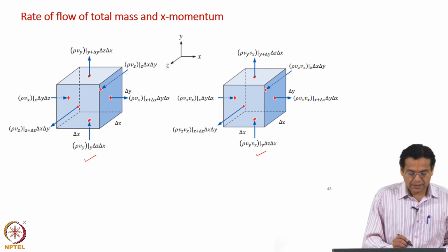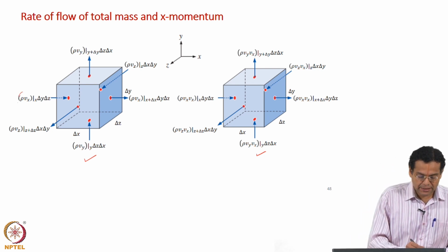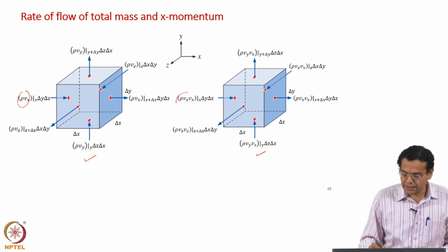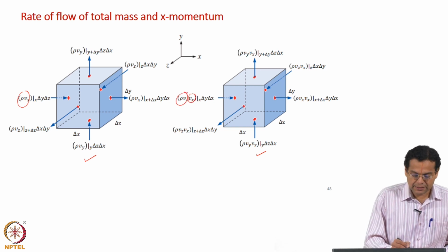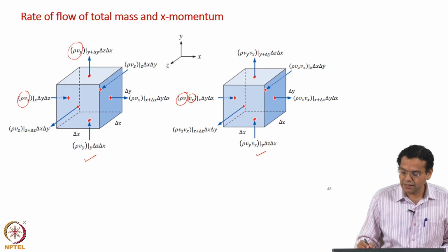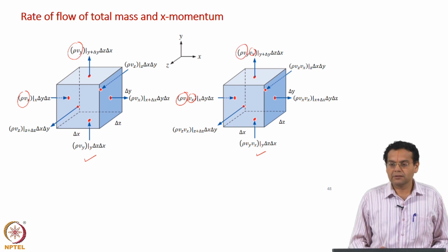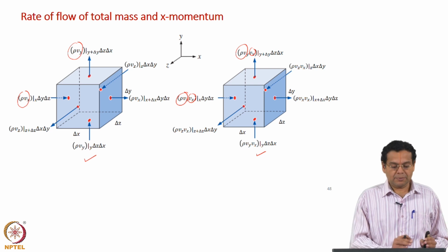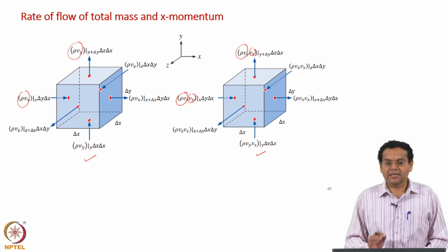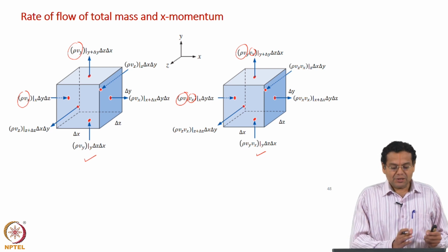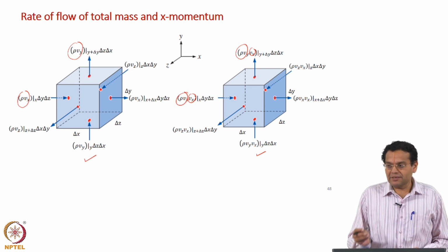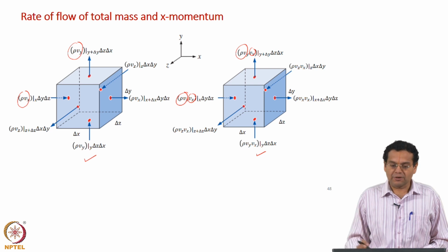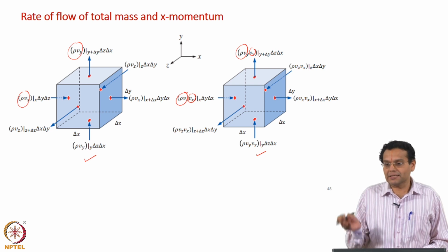What is the difference? For example, you have rho Vx here, you have rho Vx into Vx here. If you take for example this flow, we have rho Vy, I have rho Vy into Vx. In fact, that is how I generated this figure also, copied this, pasted here and edited all by adding a Vx. So, that shows that if you multiply with the Vx, you get the x component of momentum. Suppose if you are writing y component etc., you will multiply by Vy all the terms.